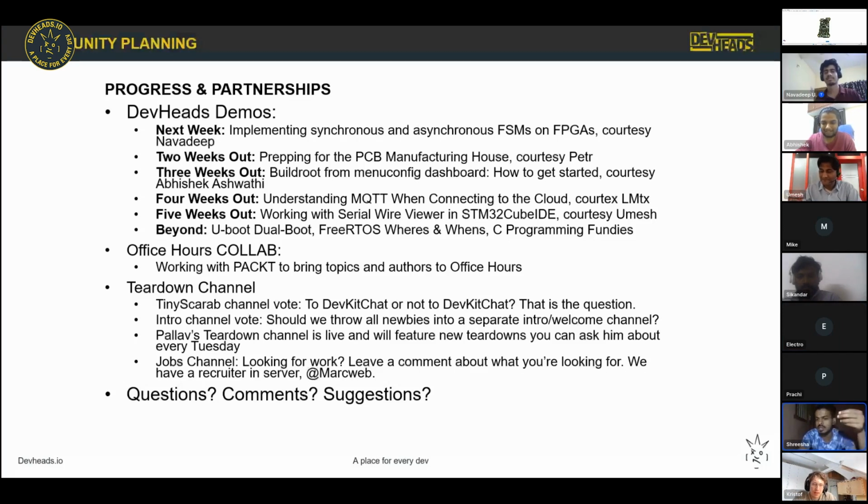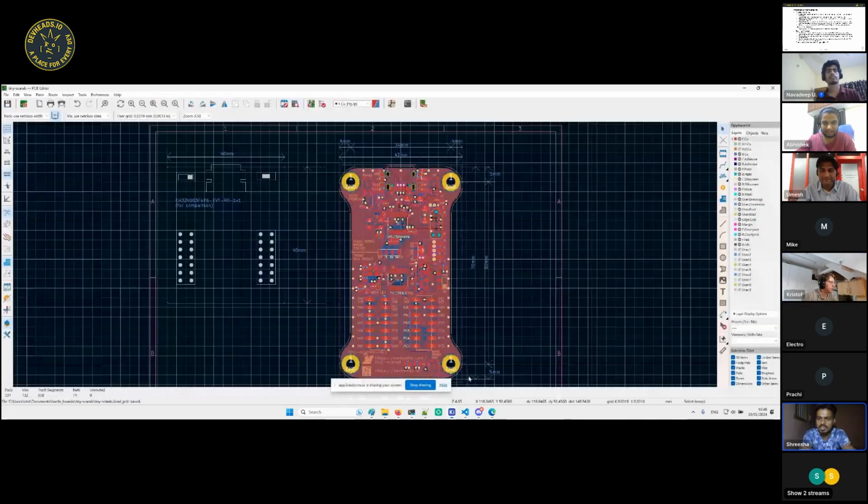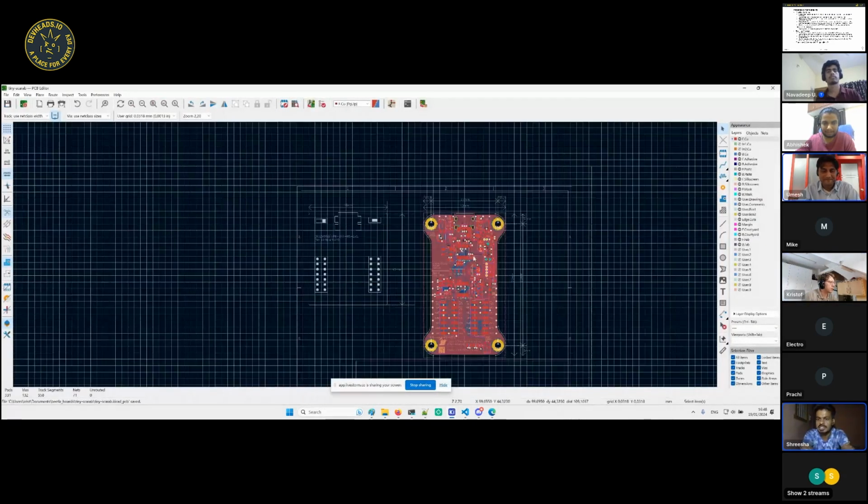I think it's possible in the PCB layout. In fabrication, I think you can produce the step file directly. Okay, I don't think so. It's available in the 3D view, but in the PCB layout, is it there? In the PCB designer, yeah, there I think you can produce it. In the export, I think you can get the entire step file.